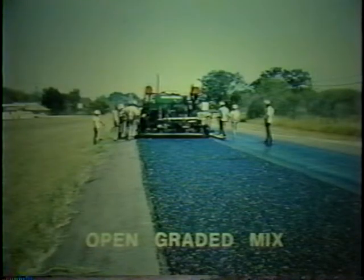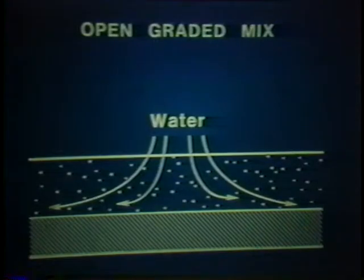To enhance drainage even more, open-graded asphaltic paving mixtures are used. FHWA specifications for the mix are available. The open-graded mix was developed to produce a surface that would allow surface water to flow down through a porous thickness and then out to the side on a smooth surface. Although the open-graded mix will not substitute for good cross slope, it does aid friction. Water in front of a tire can flow down through the pavement voids and away from the tire. Removing water from under the tire reduces the potential for hydroplaning.